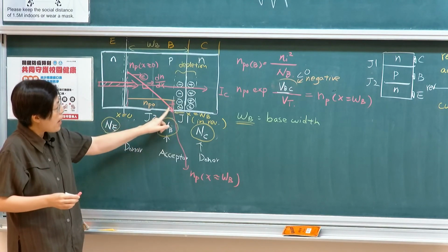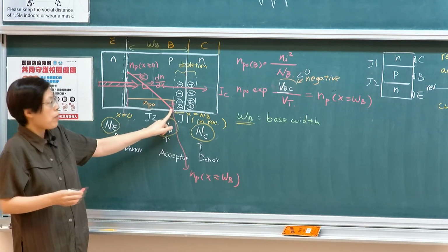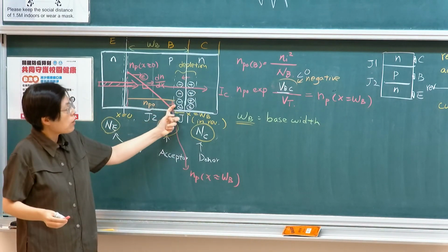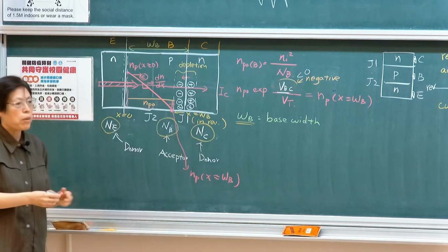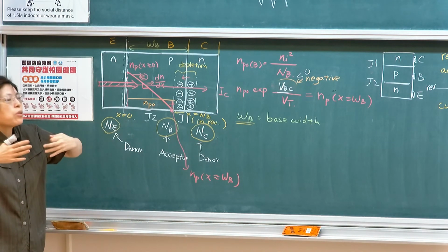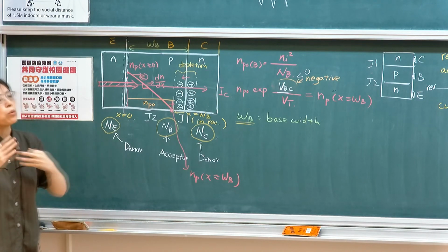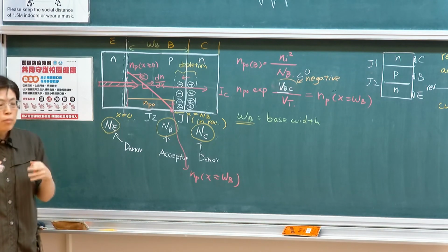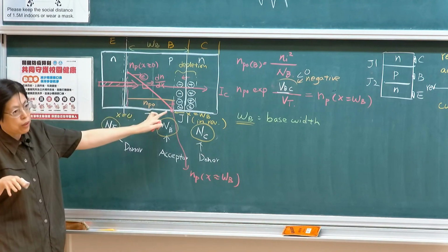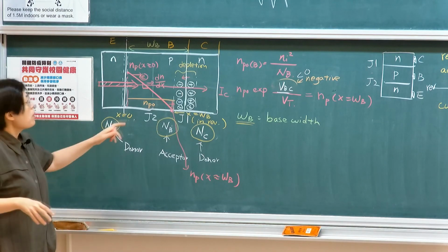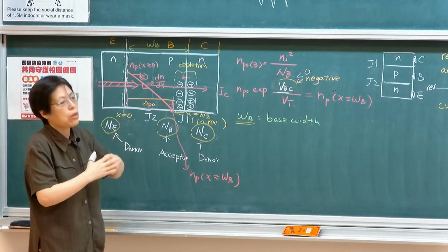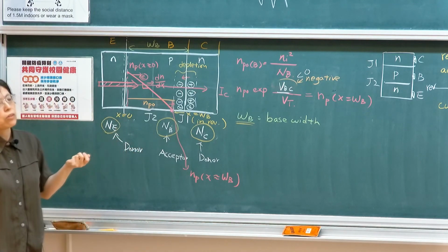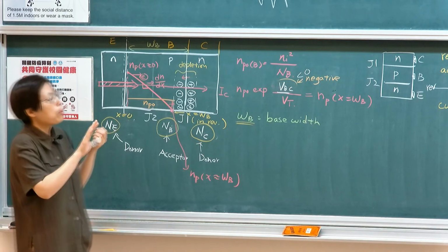So if you think about it, if I have electron diffused at this edge, it will be sucked by this electric field. I have a large electric field going this direction, pushing electron through the gauntlet. Remember, there's a large diffusion. So the reason why a typical reverse bias PN junction does not carry current is because there's no carrier. But I'm feeding carrier through this diffusion. I'm feeding it through so that once it goes into the depletion region, it will be pulled over. So one electron comes, it will just go over. So you have large electric field to pull it.